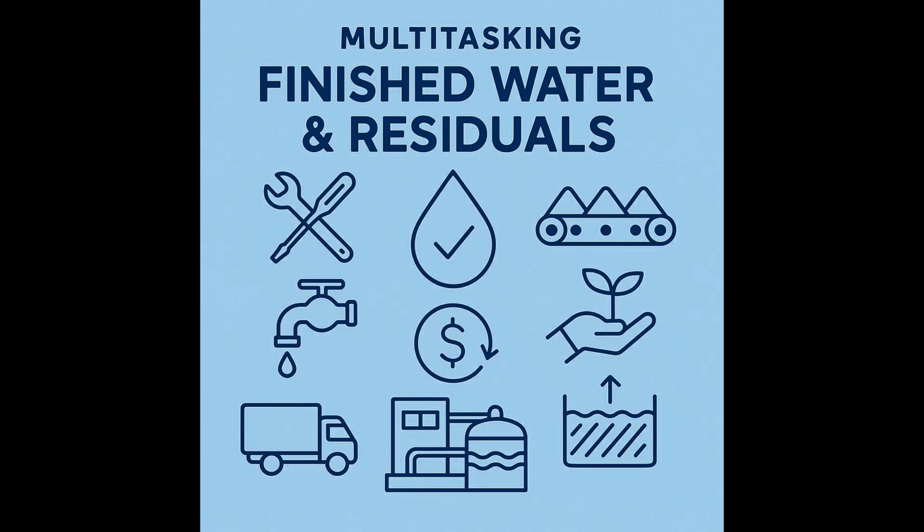2. Engineer for reliability. Invest in automation where it makes sense. Polymer systems, conveyor interlocks, absolutely install truck scales and implement standard operating procedures, SOPs, for weighing tare and gross, tracking load tickets, and monitoring driver turn time as a key performance indicator, KPI. Right-size your storage to provide a buffer for bad weather or trucking delays.